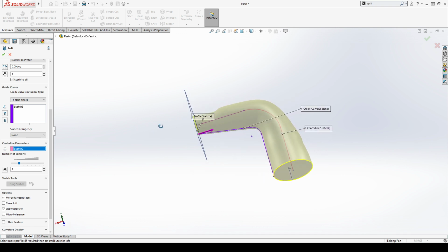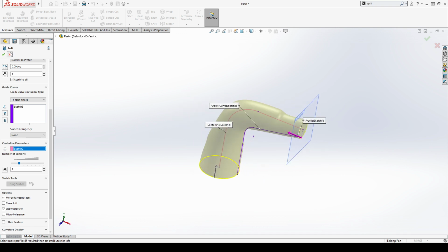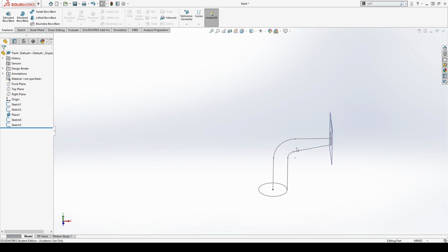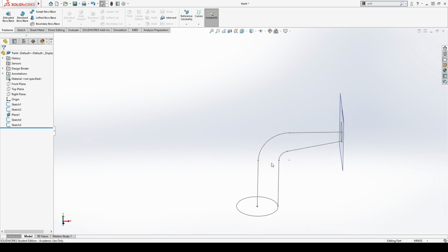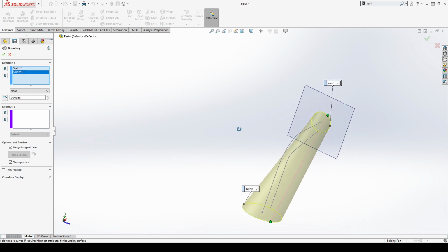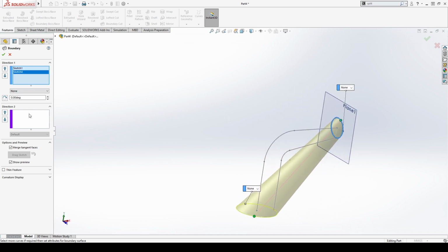All right, so it looks like I'm going to have to go and revisit my notes on lofts, which is a shame because these can be really powerful. Basically, what I'm trying to do, as you hopefully gathered, is to make a straight pipe go here, curve, and then funnel down into a nozzle. Boundary might be the option to go with as well. Let's try that out. So loft, sweep, and boundary are all ways of kind of taking profiles.